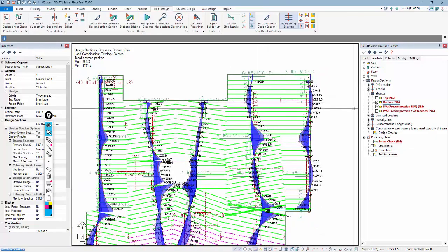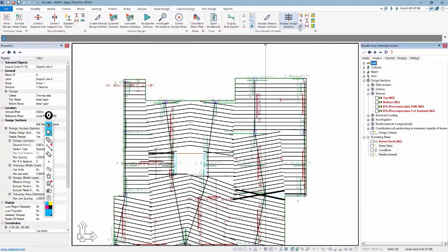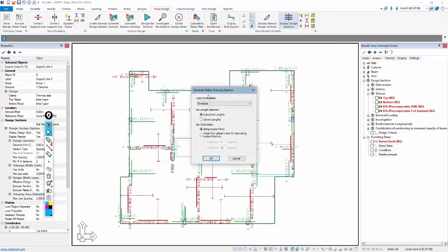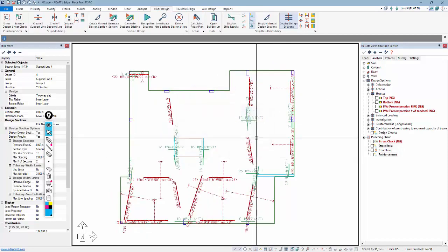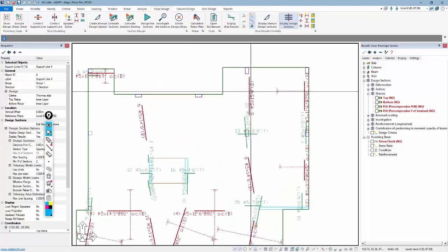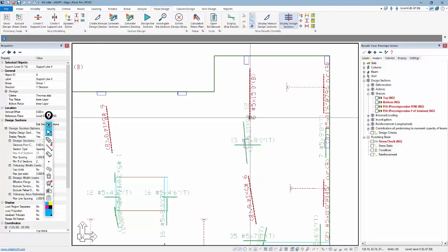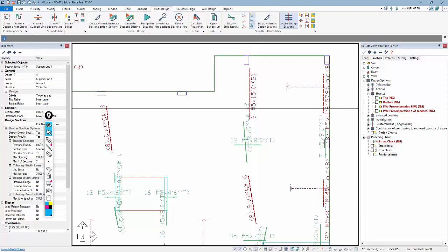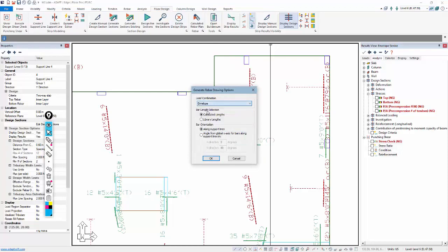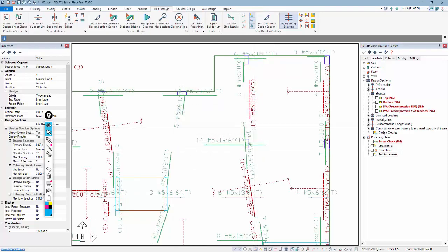So this is an output of the minimum reinforcement. If we go back and we look at the strength reinforcement, I'll go back and just envelope strength instead of service. This now is the output of the strength reinforcement. And you can see there may be more bars for strength at the same position that there might be for service. Back to that example, for strength at this location, I need 6 number 5 bars. The tendons contribute quite a bit to the capacity of those sections. And if I go back and toggle that to service, envelope service, I need 12 number 5 bars. So service would control in that region.